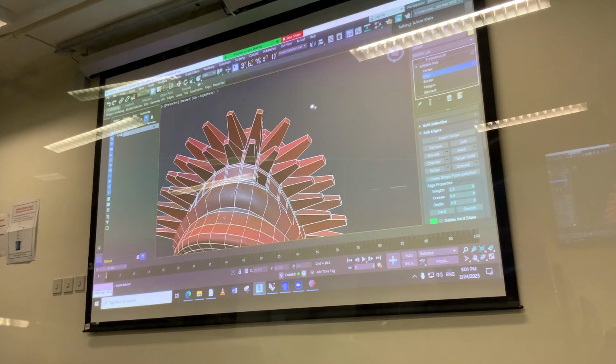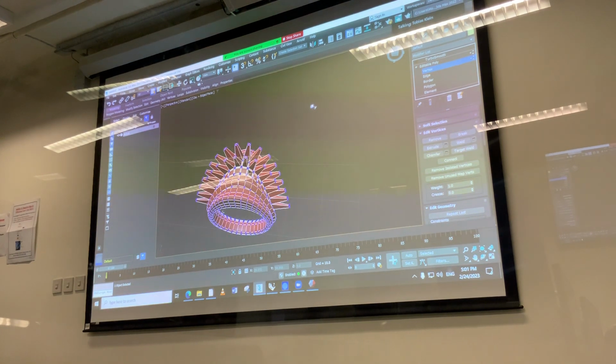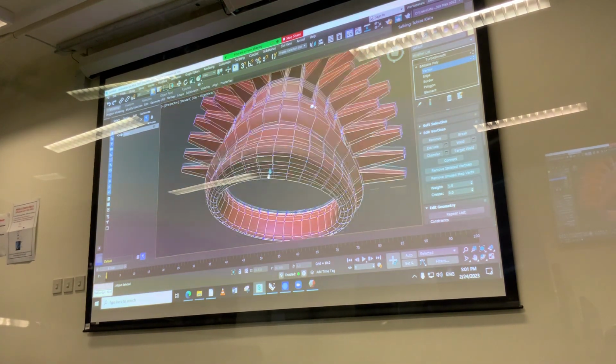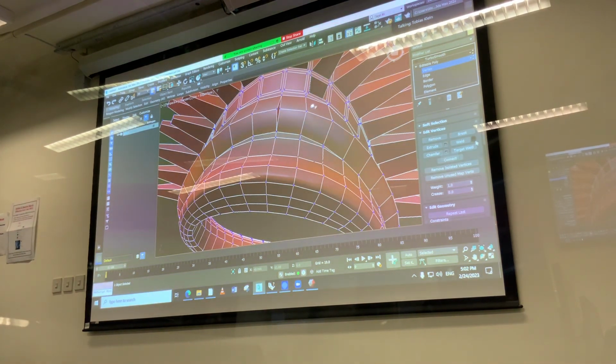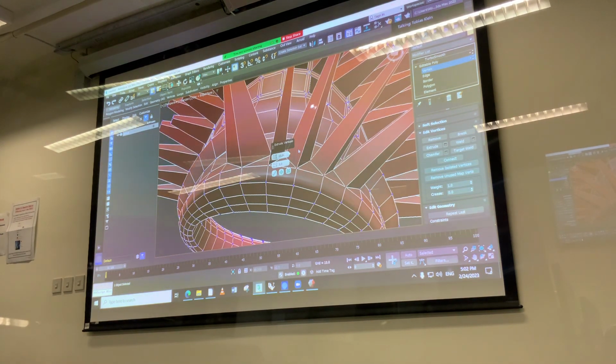The same counts then for our points. You can work with the vertices here. You don't have a ring, of course, because they are not ring connected, they are individual points. But yes, you could use the points, for instance, to make a different type of spikiness, because if you extrude these guys, or chamfer them, actually let's do extrusion.